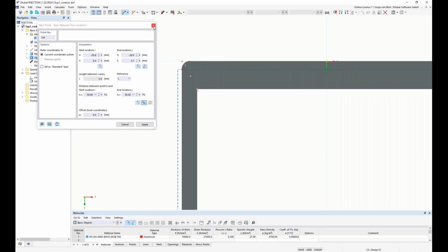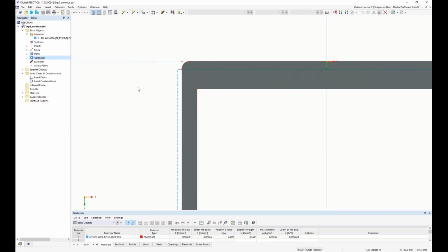I don't want to do this today because it's also a good idea to create the center lines in the CAD application and import them as a background layer. In contrast to the DXF import, in which the complete model is imported, converted into points and lines, the background layers represent a kind of layer for modeling.